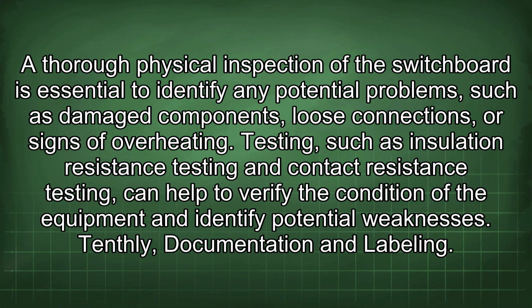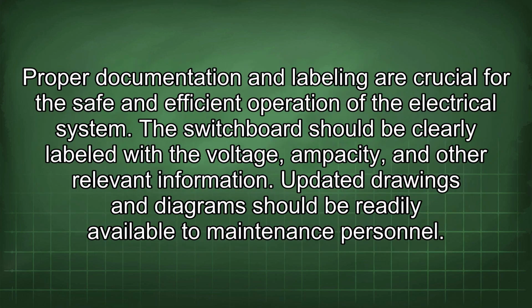Tenthly, documentation and labeling. Proper documentation and labeling are crucial for the safe and efficient operation of the electrical system. The switchboard should be clearly labeled with the voltage, ampacity, and other relevant information. Updated drawings and diagrams should be readily available to maintenance personnel.